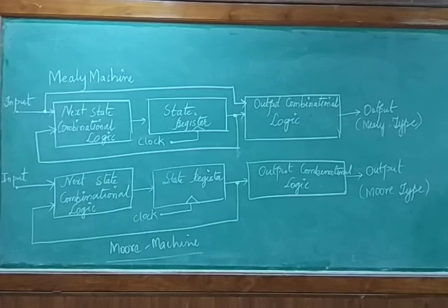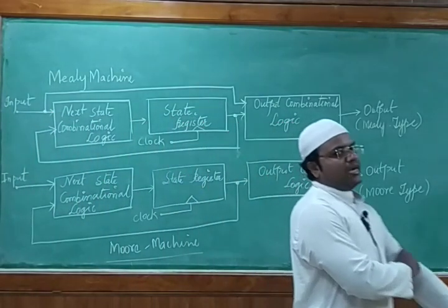So here, students, we have learned that the Mealy machine and the Moore machine are both functions of the present state. In Moore it is only a function of the present state, whereas in Mealy it depends upon both the present state as well as the input. So just draw these two things. If they ask you to design, you can explain FSM for both of them and write about the Mealy and Moore machines. Both can be designed using a state diagram and state table.